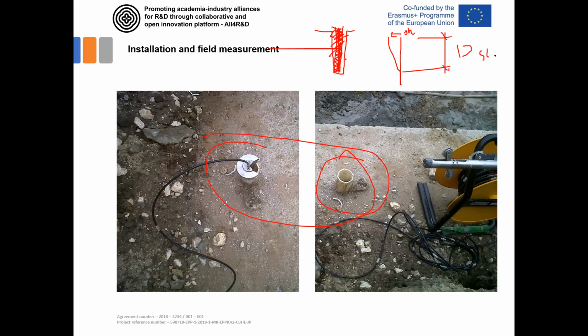Of course, when we have the inclinometer measurement, we always have some point at the bottom that is fixed, because all the displacement we get by the inclinometer is relative displacement compared to this point. If the true displacement goes like this, you'll never get this displacement by inclinometer. You can only get this line. You don't know what the displacement of this bottom point is.